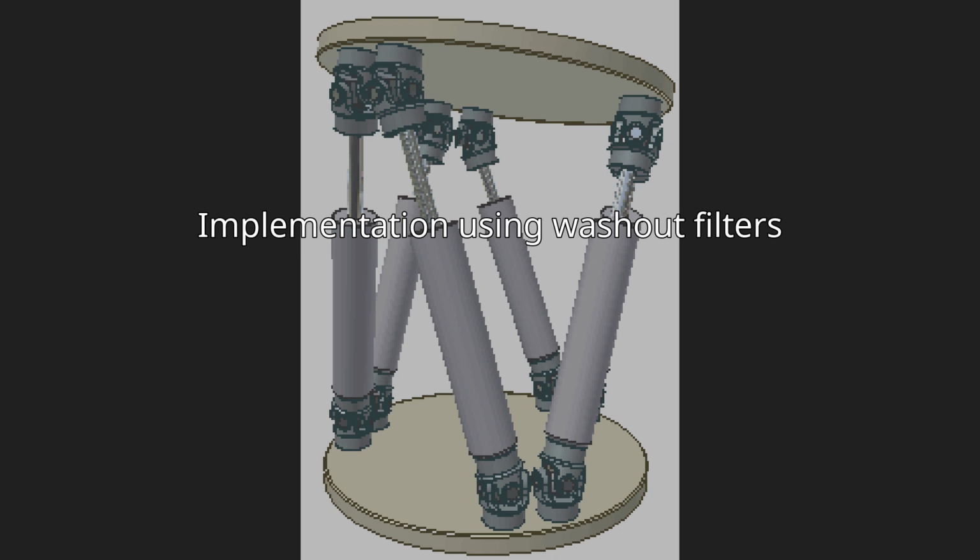High-pass filters are used for simulating transient translational and rotational accelerations, while the low-pass filters are used to simulate sustaining accelerations. The adaptive washout filter uses the classical washout filter scheme, but utilizes a self-tuning mechanism that is not featured with the classical washout filter. Finally, the optimal washout filter takes into account models for the vestibular system.